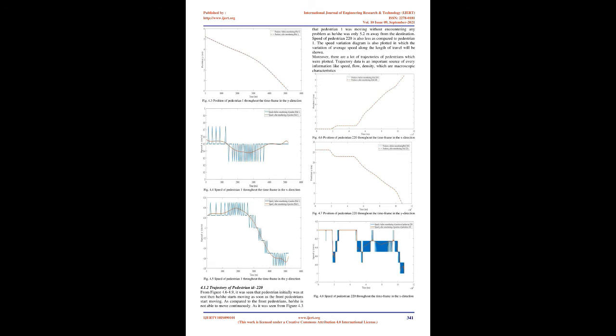Parameters of the model. A total of 5 parameters, out of 8 parameters, of the social force model have been chosen for calibration with the help of sensitivity analysis. These are strength of the interaction, A, interaction range, B, relaxation time, desired speed, and lambda. We have represented the pedestrian as a circular shape with a radius of 0.2 m.